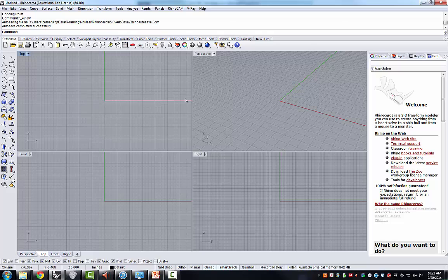The main characteristic that you will see is a 4-viewport working area in the middle. The viewports represent perspective view, top view, in other words, plan, front and right-hand views, with X, Y, Z coordinates being indicated to help you understand whether you're looking at the XY plane or the YZ plane, or looking in three-dimensional space where X, Y, and Z are located in the orientation as shown.